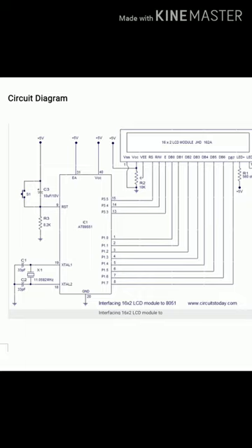So whatever you send on P3.5 will be received as a register select. If you send 0 on P3.5, it means that the data that you will be sending from port 1 will be a command, and that particular data which is received at DB0 to DB7 now gets stored in a command register.